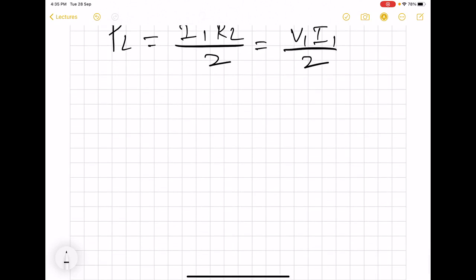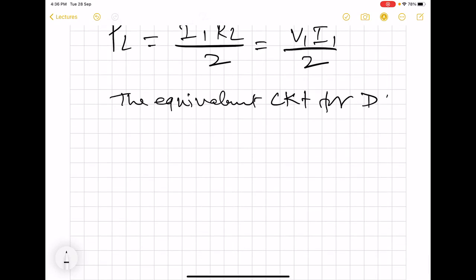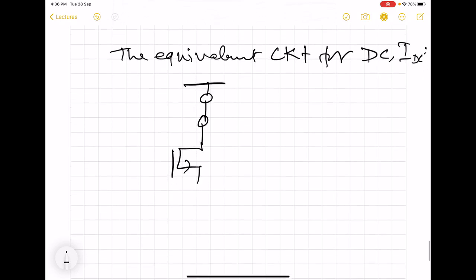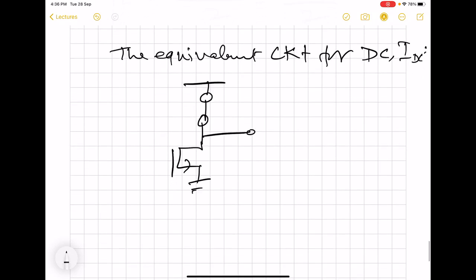So we can see the circuit, equivalent circuit for all those harmonics. IDC. So for this, RFC will act as a short circuit and blocking capacitor open. So IDC flows in this way.